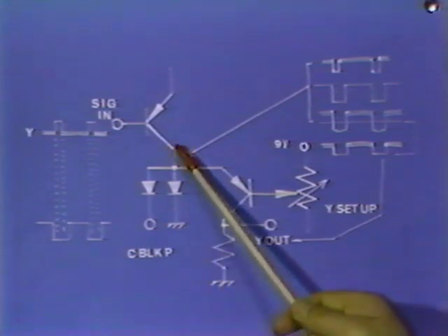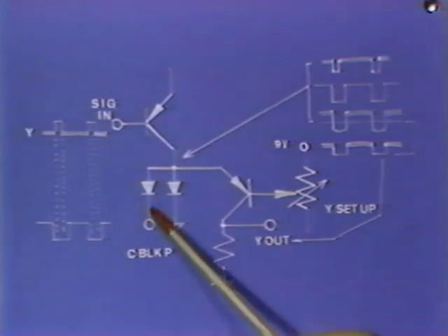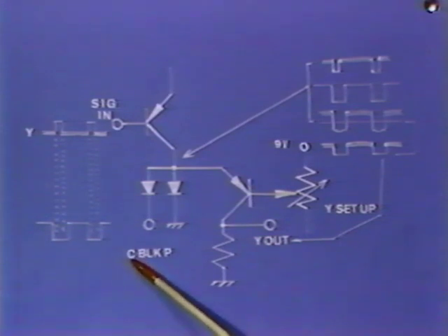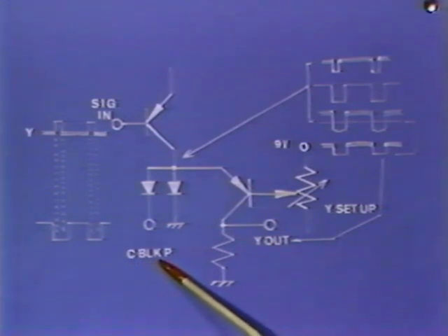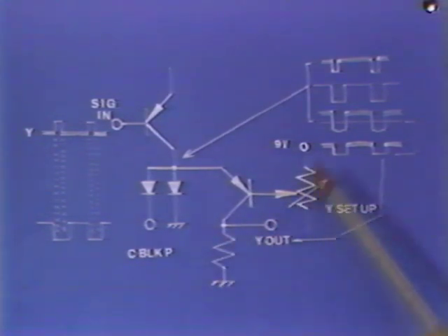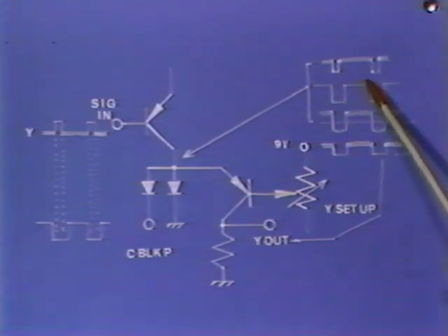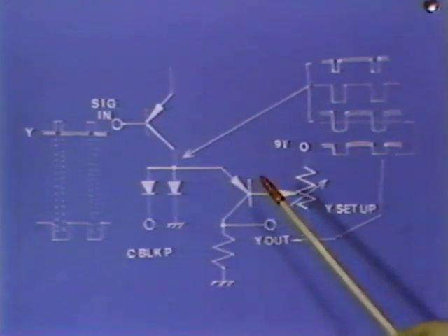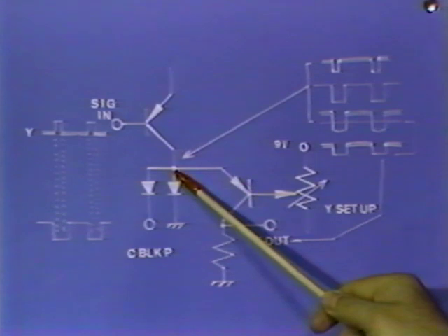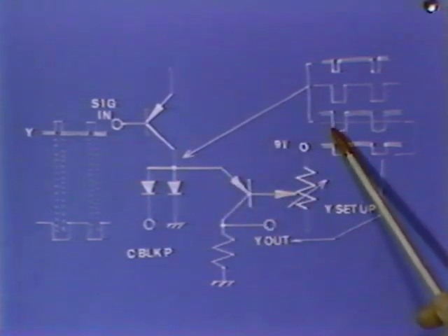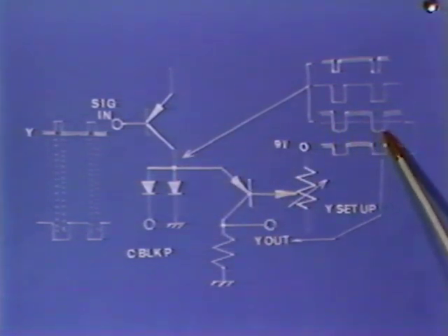On the other hand, the X225 collector receives the blanking pulse through D201. At the X225 collector, this wave pattern of the sum of the image signal and the blanking pulse is seen.